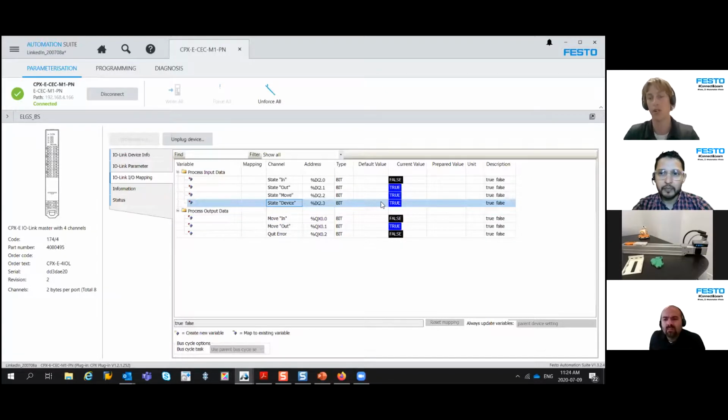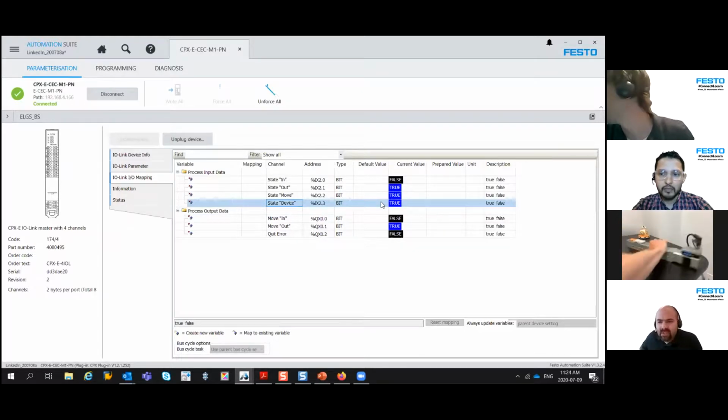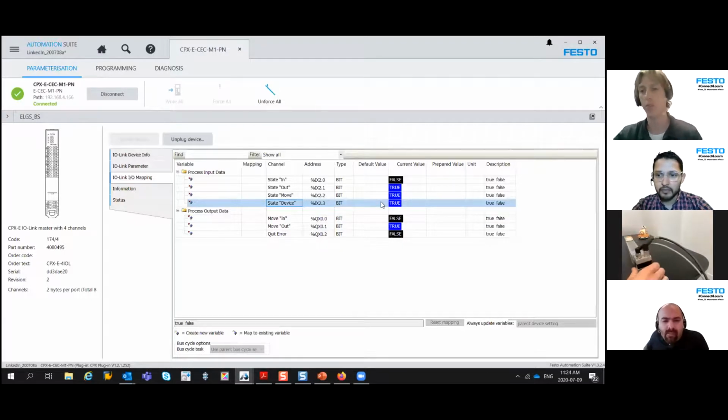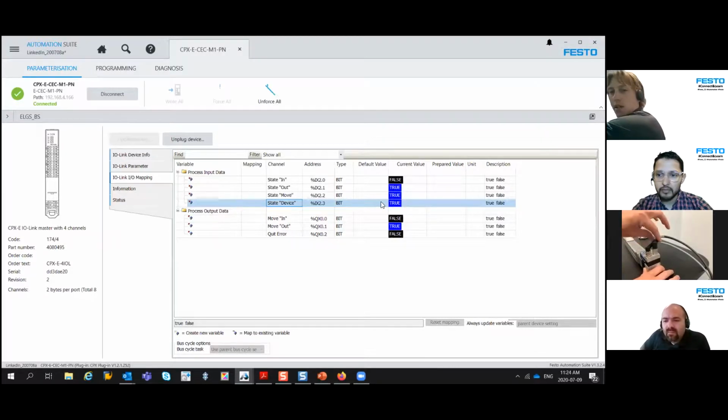They're on separate connectors, so you can tie that into a safety relay and cut that line. If you're doing a part load/unload station and you want to disable the power stage so an operator can retract and load a part, you can disable the power to this connector right here, which is your power stage, and now it's disabled.